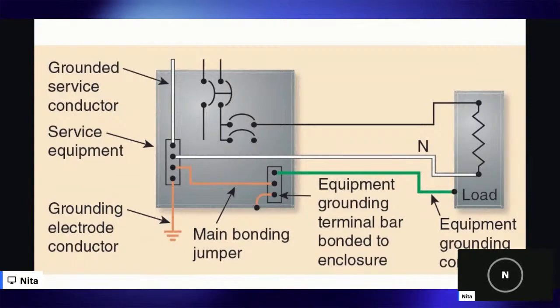This should make the reading easier to understand. There's more than one type of grounding electrode. I'm just talking about the ground rod because that is common and easy to understand, but you can also have other types of grounding electrodes. So yes, you do want to be able to identify and confirm that one is present. It may not be a ground rod.